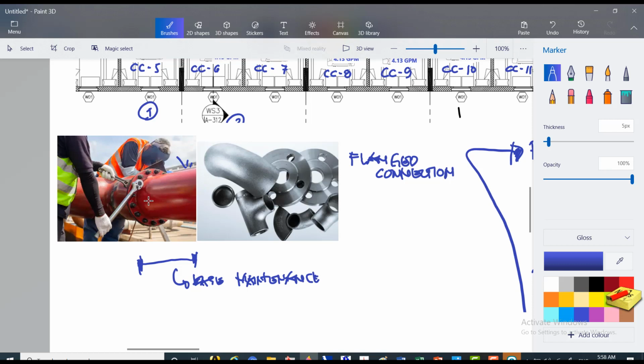So we do flange connection, so we weld the flange outside the building, and then pag clear na yung building, wala nang gumagamit, papasok yung installer, then we can do piping by means of flange rather than by means of welding.